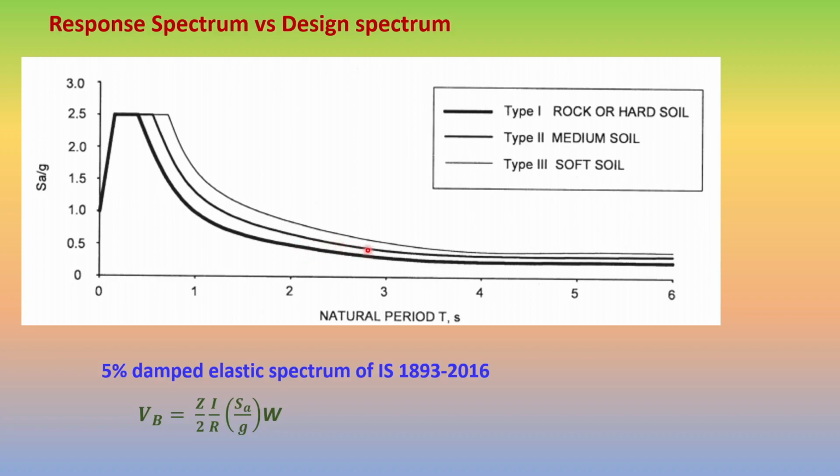Each of these earthquakes will have its corresponding response spectrum. Here in our code the acceleration response spectrum is given, because the vertical axis is the acceleration axis. If you take 500 response spectra, or 500 earthquakes, and take an average of all these, then it becomes the design spectrum for the country.